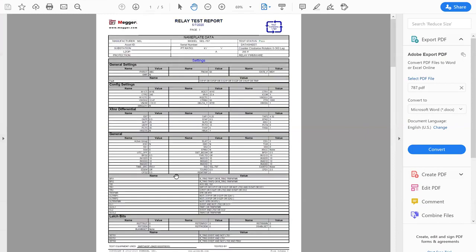Either you can do single phase by providing just one current to the neutral CT, and then you connect the 3 phase CTs in the zero sequence fashion, and then give that to one of the currents on the test set. So you are using 2 current sources on the test set in that scenario. If you don't want to do that, you can use 3 current sources on the test set for the phase side CTs, and then 1 current source for the neutral CT, and you can define it that way.